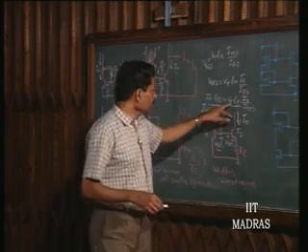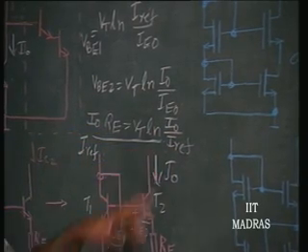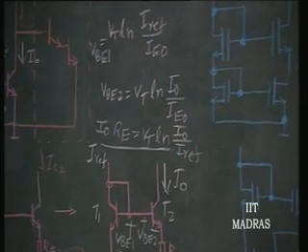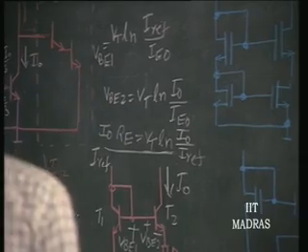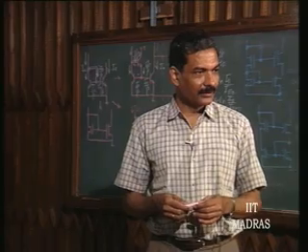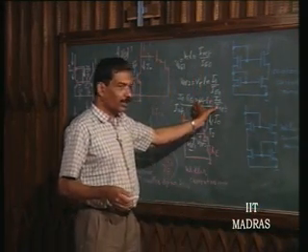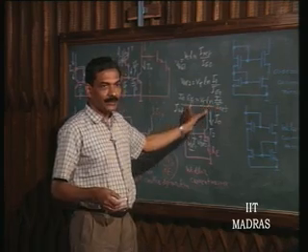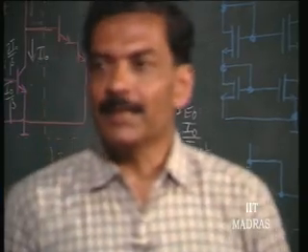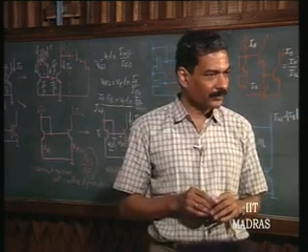So, 26 millivolts, natural log of 1000 divided by I naught will give you the value of Re required to be put in order to get I naught of 1 microampere. So, straight away the design is very simple, straightforward. Is that clear? So, we have the voltage here 25 log 1000 divided by I naught will give you the value of the resistance mostly in kilo ohms range. This is clear, I suppose.